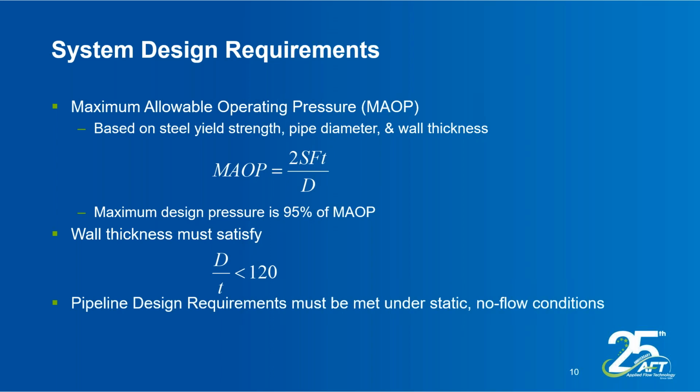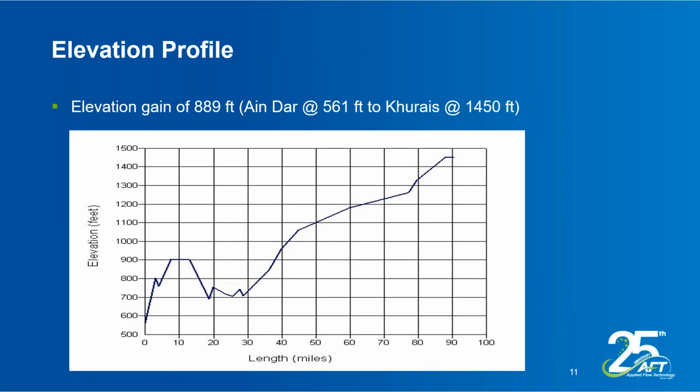Third, these design requirements needed to also be met under no flow conditions. So essentially, if the pumps were deadheading, the pipeline would need to be able to handle all of that.